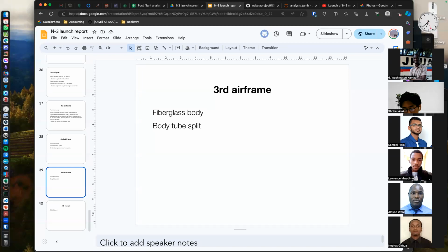Equally, the placement of the bolts, if you look at the tearing, you see it was just longitudinal. One bolt takes a day. I wish the next time we do it, we try to balance the points of failure rather than giving it a directional tear. We might arrange the bolts in a manner that they do not amplify the stresses, but rather reduce them. So the way we design the positions of the bolts should also be an element.